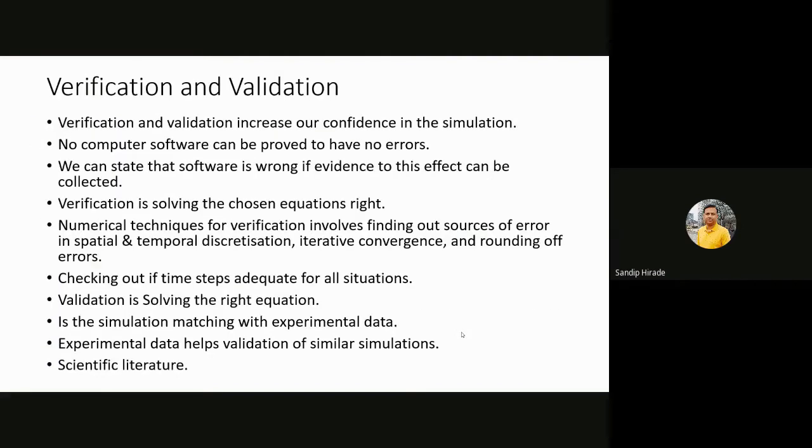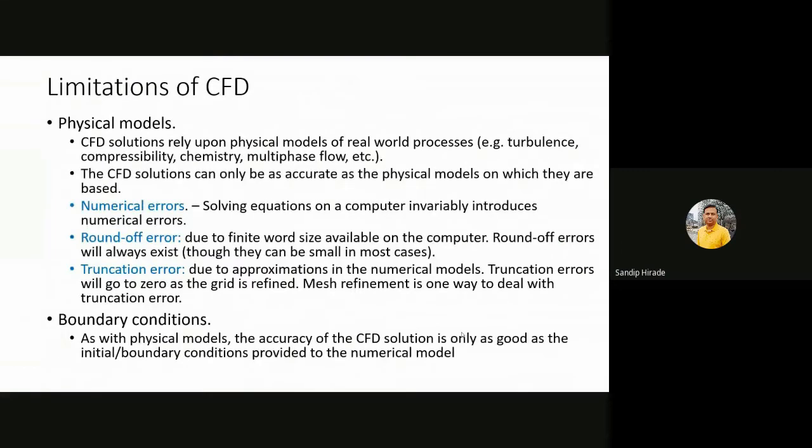And then once you are done with that, you verify your data with the test, you verify the computation with some small hand calculation, because the CFD process has different variables and you never know where you are going wrong. So always the CFD simulation has to be verified and validated either with the test data, the hand calculation, or with the experts. So this is all about the CFD process that we have seen.